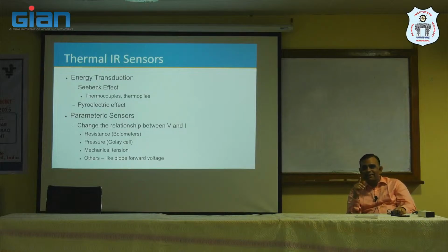It's the I naught term which appears there. That is heavily temperature dependent. Okay, so I naught times e to the power volt is something. Actually, we will see it's not a very easy relationship with temperature. As a rough rule of thumb, we say for every 10 degrees Celsius it doubles. So it's an exponential kind of change, but that's a rough rule of thumb. It also depends upon what type of diode you have, what material you have made. Okay.